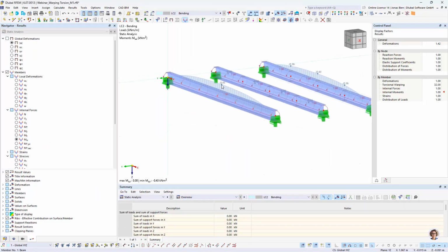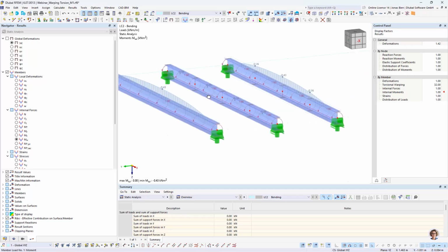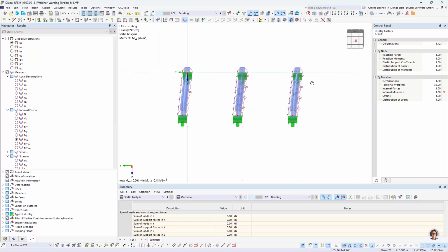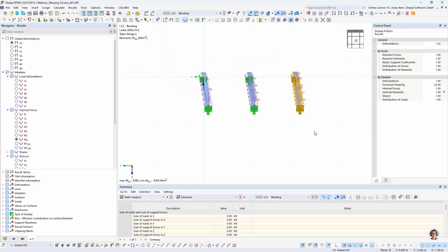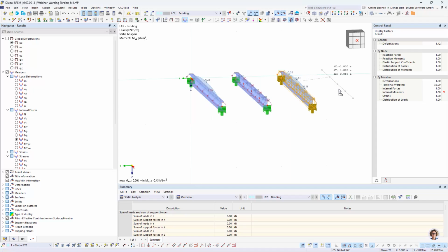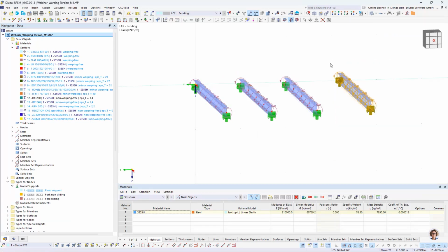And we can actually see that now at the intermediate nodes, we still have some warping moment that is transferred from one member to the other, and we get the same results. So be careful whenever you work with 7 degrees of freedom. The default behavior is that the warping degree of freedom is not coupled from one member to the other. It's not trivial in many cases how the warping degree of freedom is transferred, and we can couple them via this member set by grouping them up.